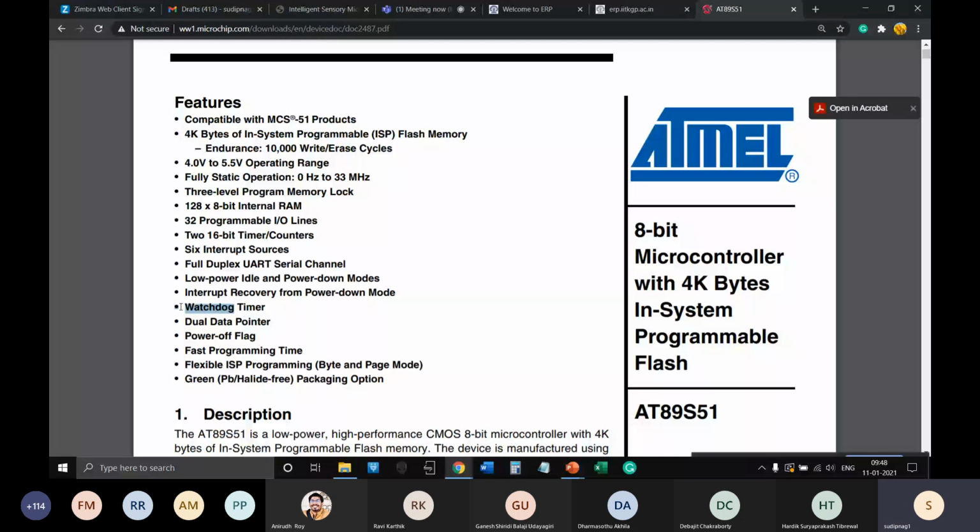So now I'll explain with the coding, actually with more detail, about the watchdog timer. We won't spend more time, but in general, we activate the watchdog timer in operating systems, and the watchdog timer keeps track that you are not elapsing a lot of time due to any wrong code that is written in the program memory, or if the processor gets hanged, waiting for an interrupt again and again, but it's not going to serve anything.